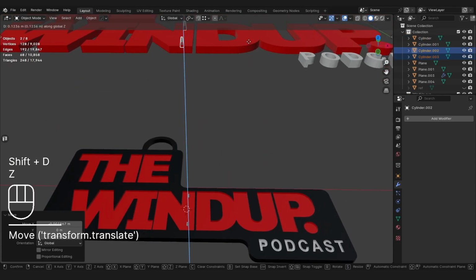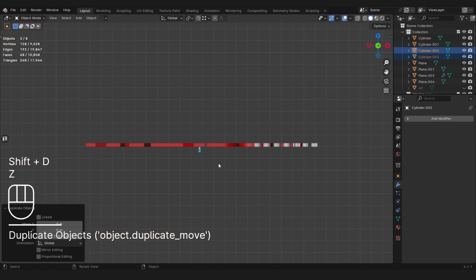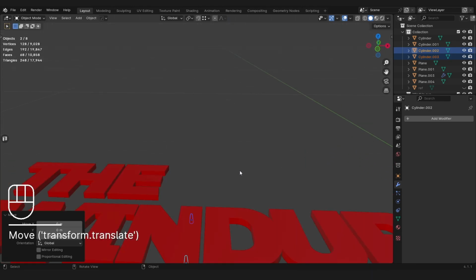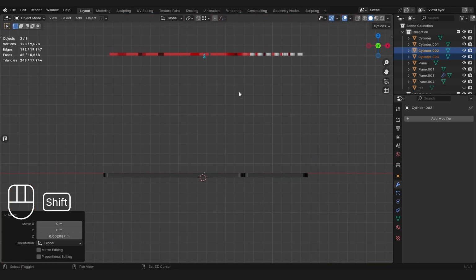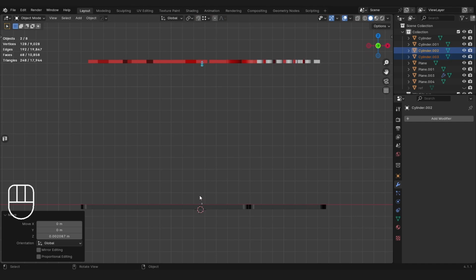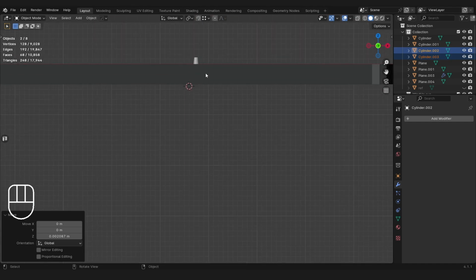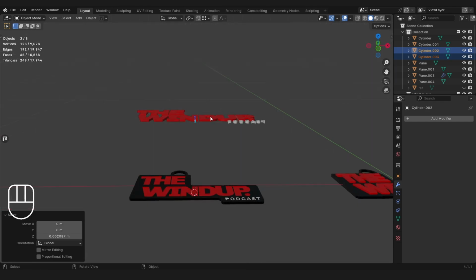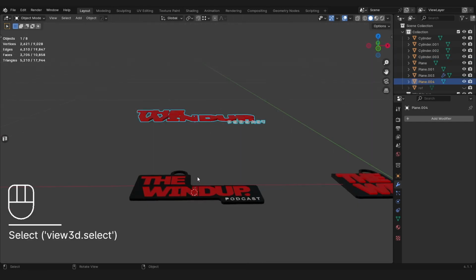And then I'll make a copy and just move it straight up, since we moved this straight up, and just sort of intersect that in there. And you would want to make sure that these are lined up correctly and you have the same amount in this as is coming out of the base there. That way you don't have too much of a peg coming up and not enough room for it in the geometry. So you might want to drop this back down and check all that first.